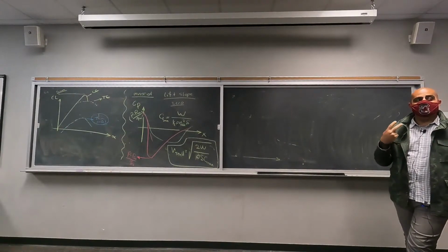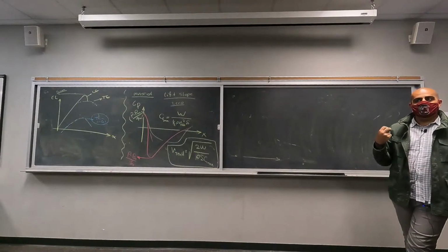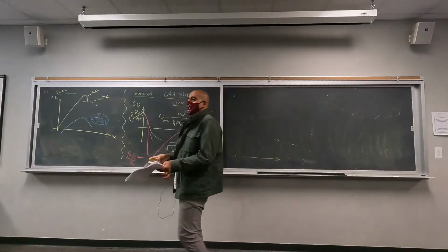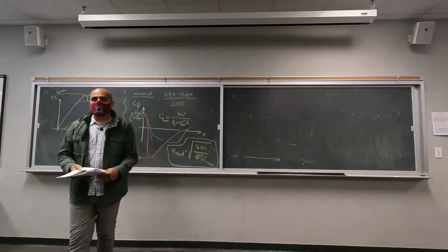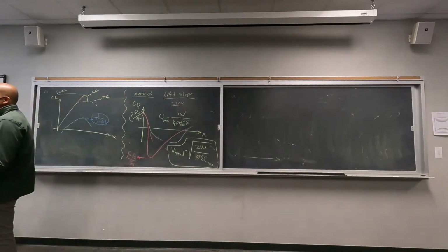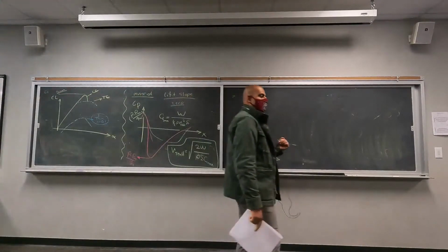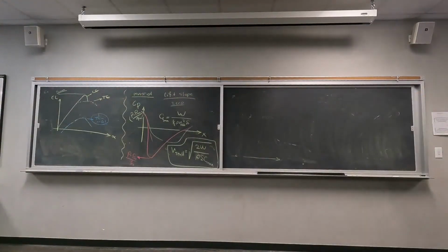So what were the two different types of airfoil we analyzed? We divided our analysis into two different types of airfoil: symmetrical airfoil and cambered airfoil, right? Cambered airfoil is going to give you negative zero lift angle of attack, right? And also higher lift coefficient. That was the idea of the cambered airfoil. So one mechanism to increase the maximum lift coefficient you are going to get out of your system is to increase the camber, right? So there are two goals here.